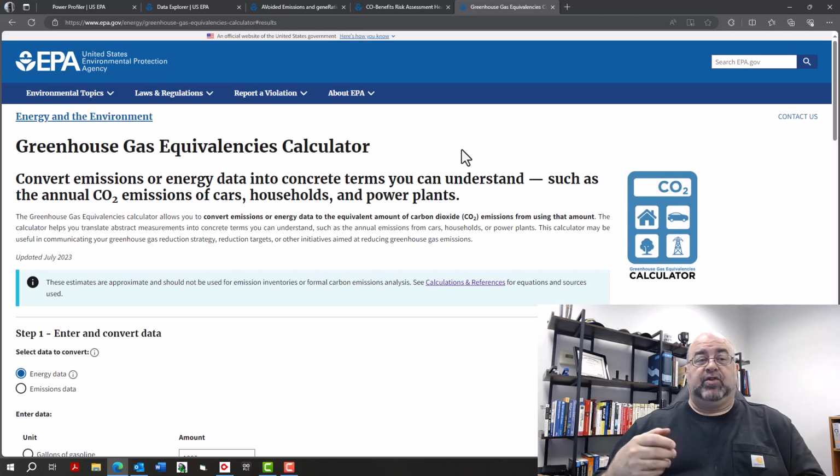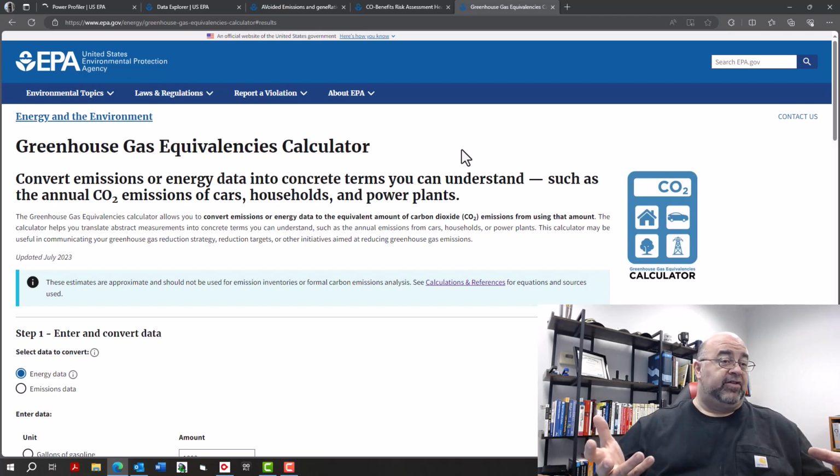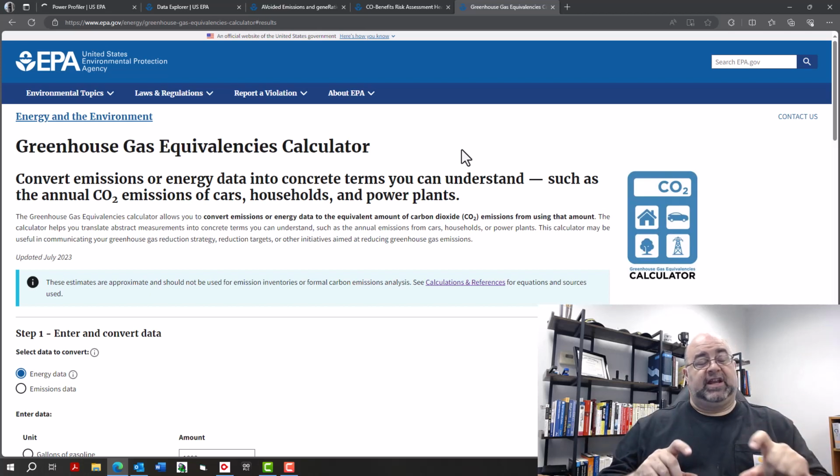So if I'm doing a precision maintenance program, say I do a precision alignment, I can take a look at my losses associated with the alignment ahead of time using a tool like Empath. Of course, I'm going to mention Empath for ESA, in which we can identify the defects, and each defect I can relate directly to energy impact. Then I can take that information and put it in here.